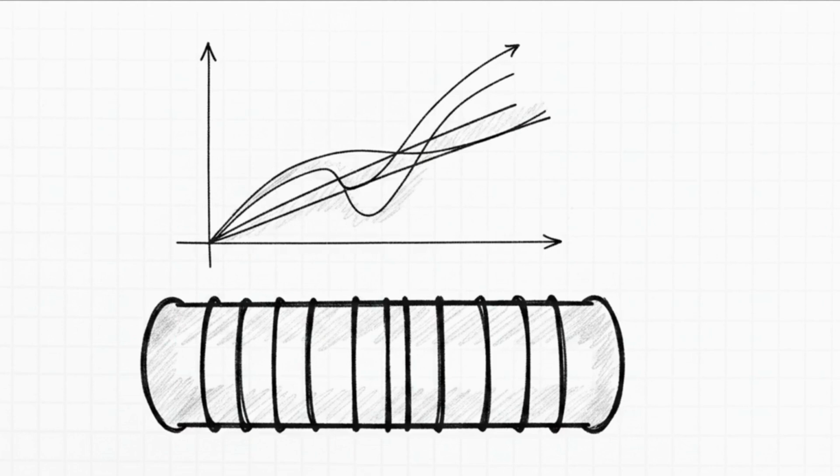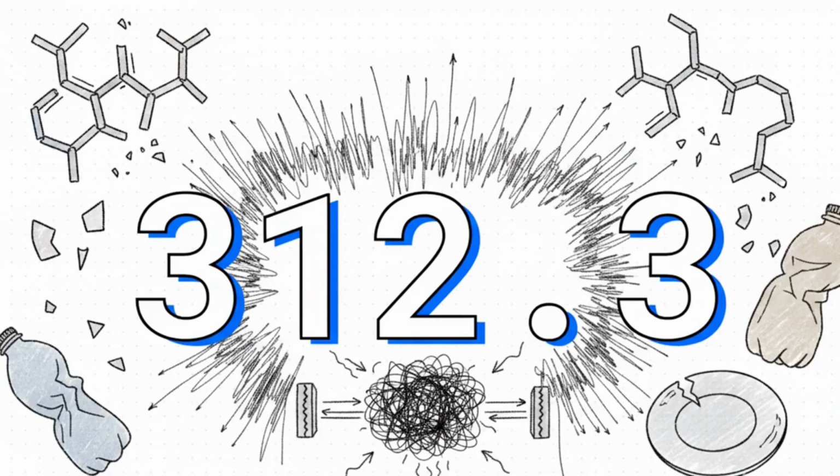The machinery possesses massive thermal inertia and really long nonlinear phase lag. If you ignore the MIMO math and stubbornly run those heaters independently, constructive thermal interference causes a massive overshoot. We're talking about driving the central core to a catastrophic 312.3 degrees Celsius. Remember the LLDPE polymer we mentioned earlier? At 312.3 degrees, you induce rapid, destructive polymer chain scission. You are instantly ruining the mechanical integrity and the aesthetic quality of the plastic. You're basically turning valuable raw material into completely useless scrap.